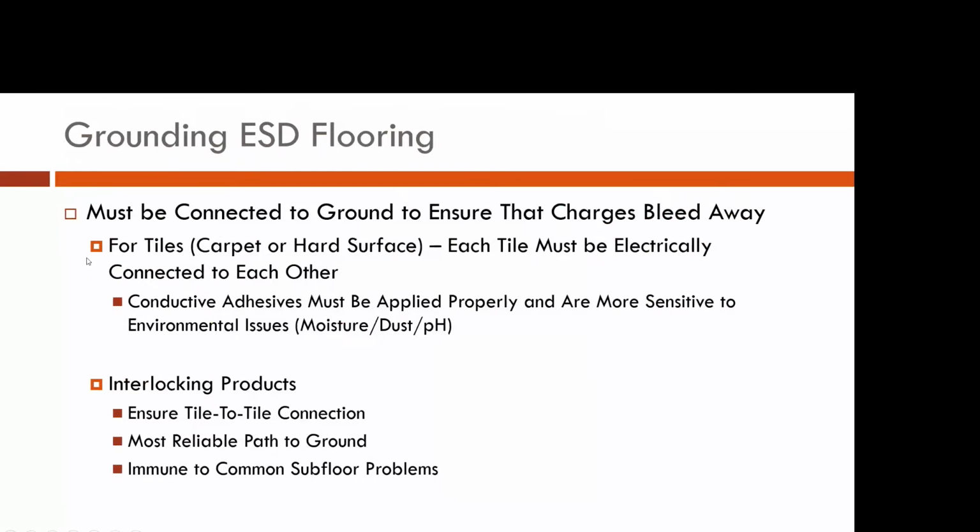So some tenets for the ESD floors: the floor must be connected to ground to ensure that charges bleed away. Otherwise, it can't happen. Things like glue down vinyl tiles or carpet tiles or painted on epoxies or rolled out epoxy systems, everything has to be connected to each other.